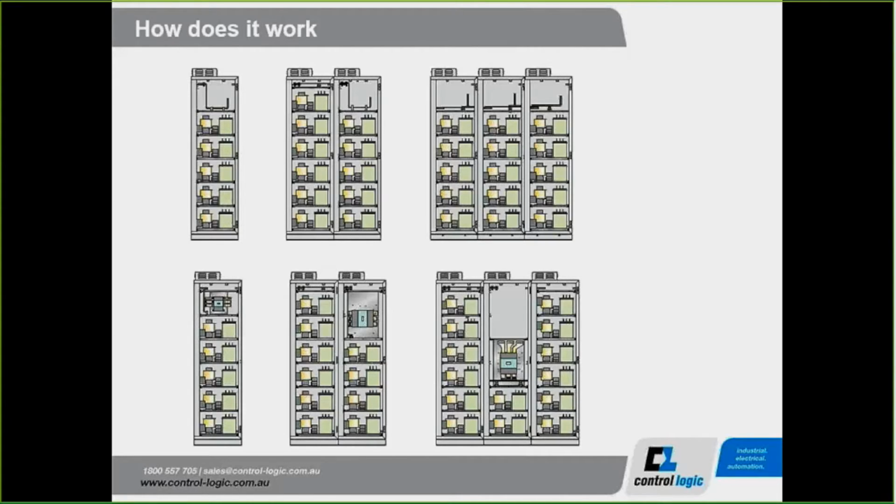And internally, two of the three phases are wired up to the power factor controller HMI. So the HMI basically knows what the power factor is, because it knows voltage and it knows current. It also knows what the load is on the network. When the user commissions this unit, they enter a number of settings, but one of the key ones is the target power factor, i.e. to what point you want to improve your power factor. Is that 0.95, 0.98, for example? These are user adjustable settings.